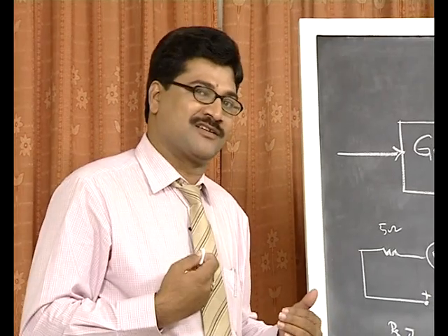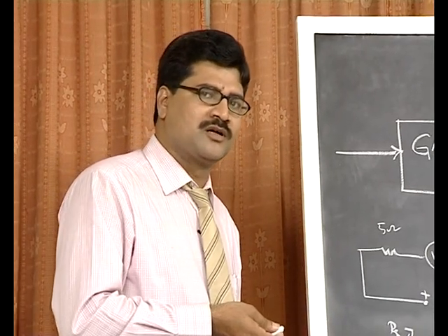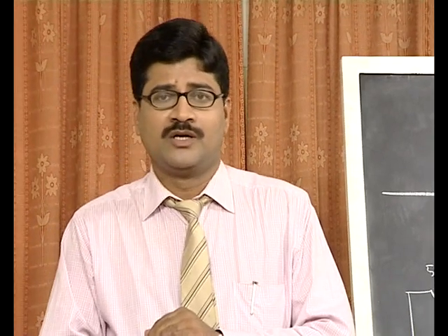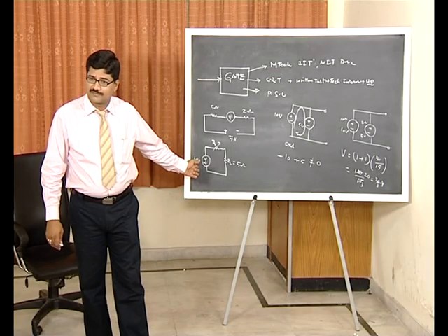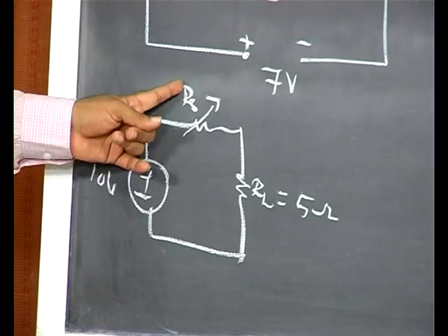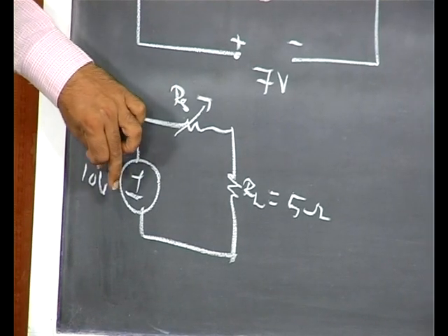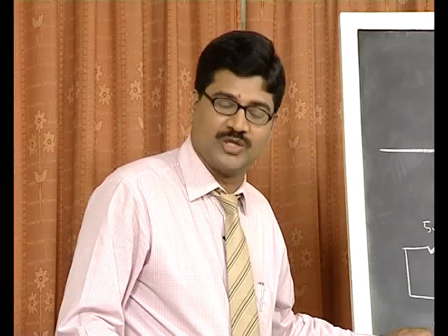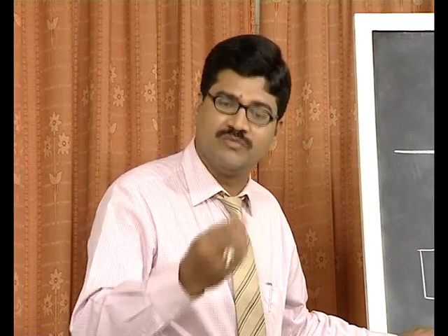So this is an unknown direction. This is a known concept, well known concept. Maximum power transfer theorem is a well known concept for you, but in unknown direction they are asking the question. This is a previous IES question. Now what's the answer? At what value of Rs is maximum power transferred from source to load RL? At Rs equal to 0, when Rs is minimum.